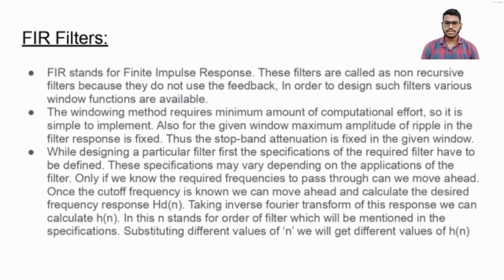Once the cutoff frequency is known, we can calculate the desired frequency response. Taking inverse Fourier transform of this response, we can calculate h(n). In this, N stands for order of filter, which will be mentioned in the specification. Substituting different values of n will give different values of h(n).